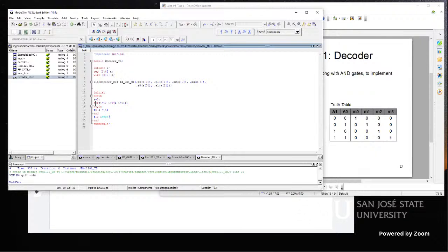Then in a loop, start with A as 0, like integer 0, which in 2-bit form is 0, 0. And then for I equal to 1 to 16, every 5 nanoseconds, I'm assigning A equal to I. Now, remember, I is an integer type, which will count all 16 values.